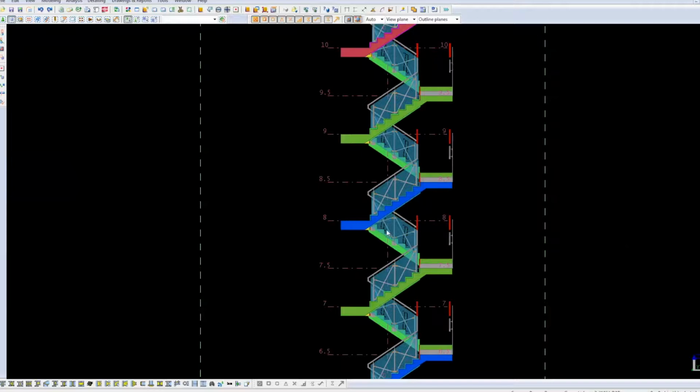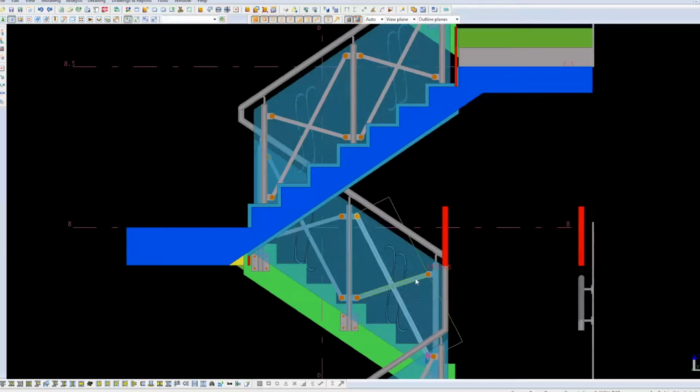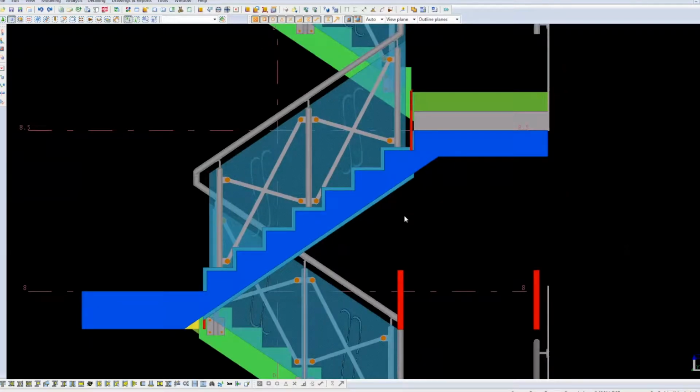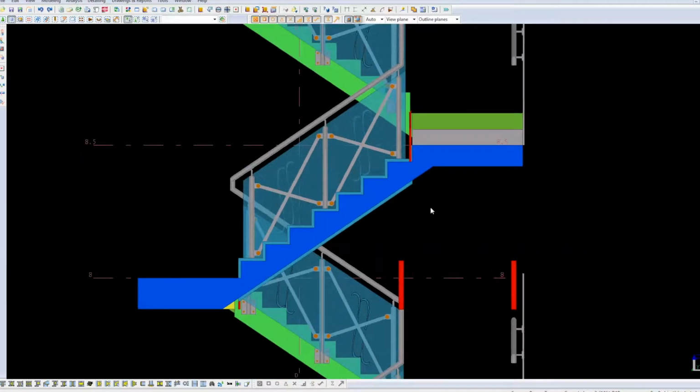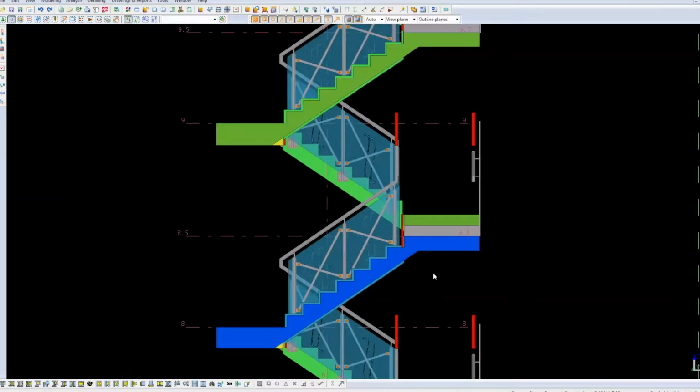This is a bit of a weird one, because it was just loose glass. These are some temporary bracings that I introduced, so that the lads on site could pre-fit these posts and put these bracings in with shot holes in, and that would set them so that when the glass came in, weeks later, it would match the post fittings, and that worked great. I don't think I had one single panel that didn't fit.